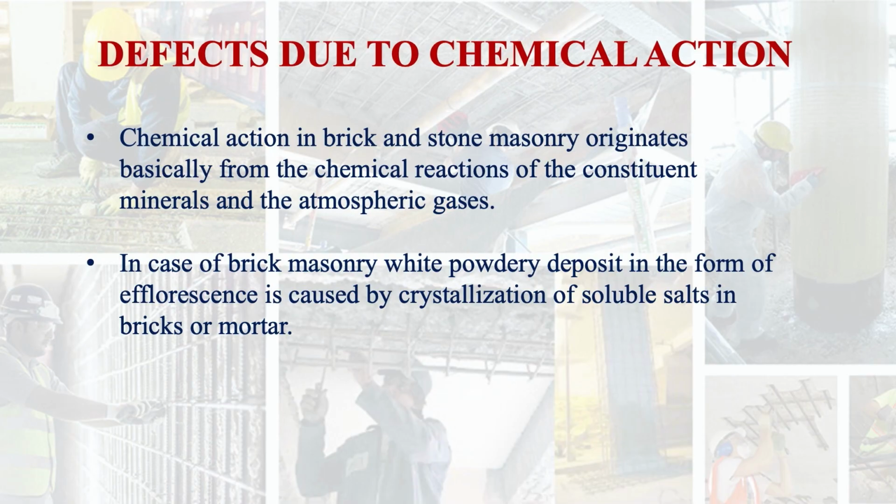In case of brick masonry, white powdery deposit in the form of efflorescence is caused by crystallization of soluble salts in bricks or mortar.